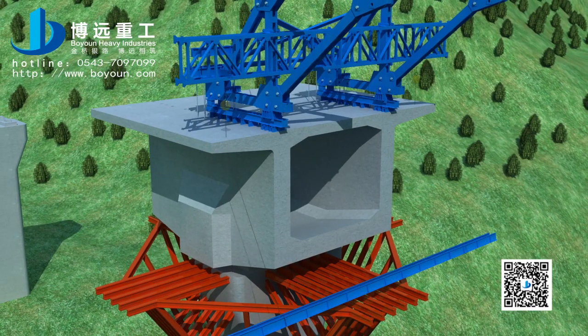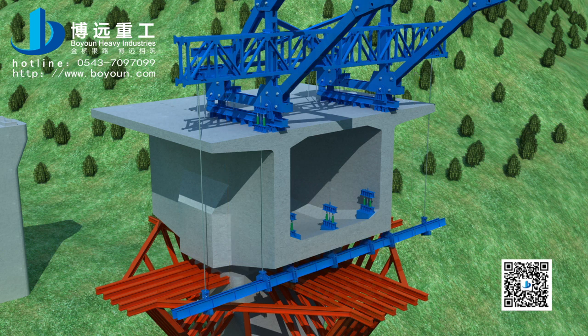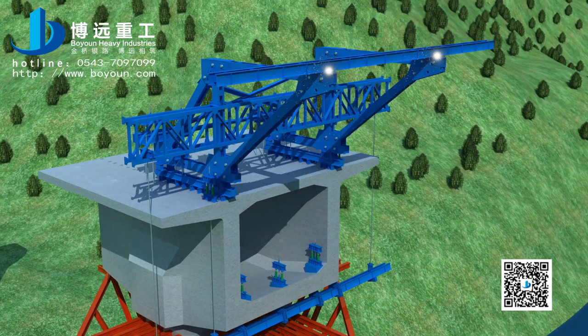Install rear joist through the bottom formwork reserved hole, hanging rear joist in place by hangover rod and hangover frame at top and bottom to connect and fix. Install the front upper cross girder, weld and connect to diamond frame. Install carrying pole beam and hanger rod.